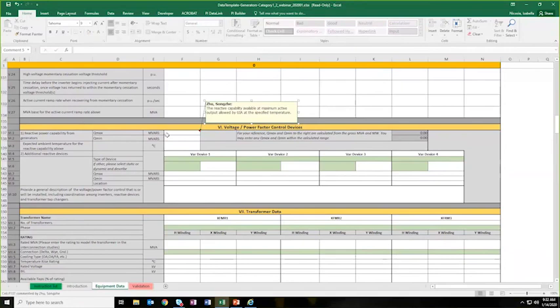So there are multiple reactive sources. First is the generator. You tell us a total number, so if you have multiple generators, enter the sum of the Qmax and Qmin from individual generators. Also, when you enter those numbers, we want to know what temperature you assumed. And a further clarification: these Qmax and Qmin are the Qmax and Qmin at the output that you will produce at the terminal to achieve the megawatts at the POI.